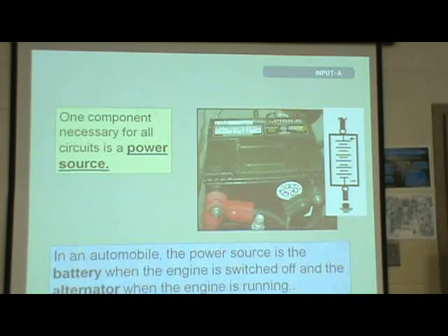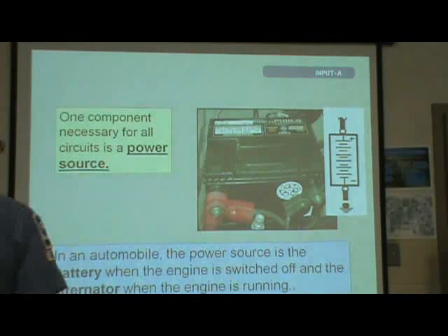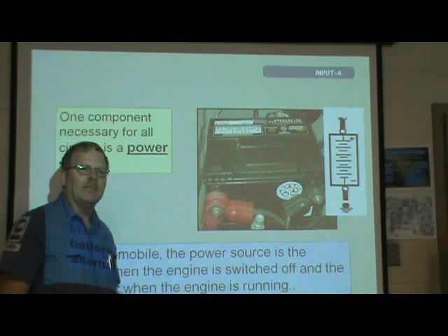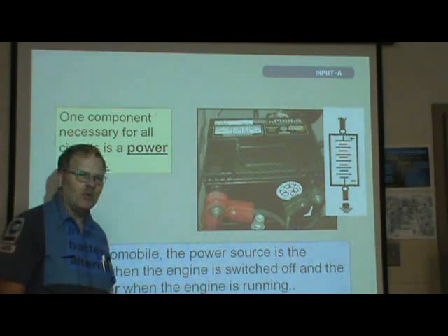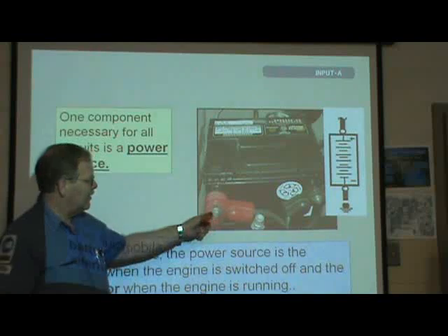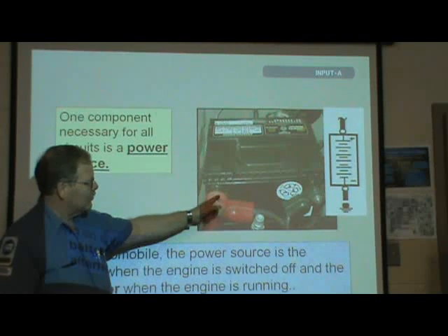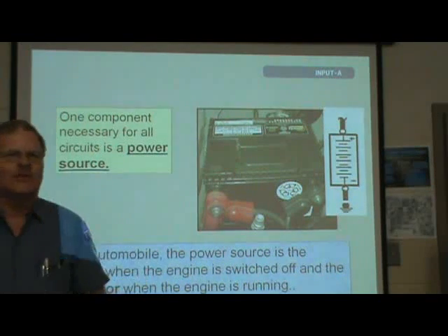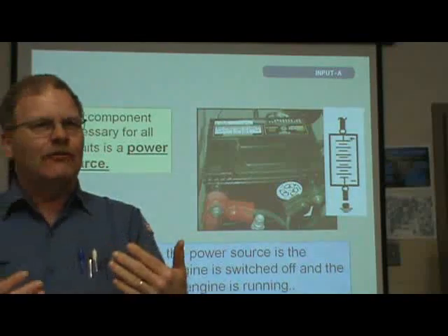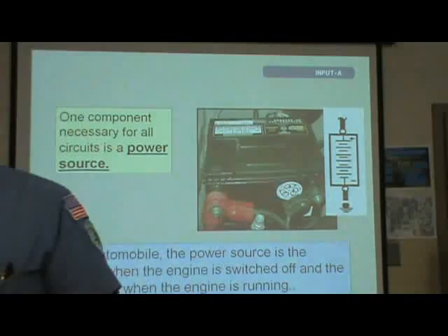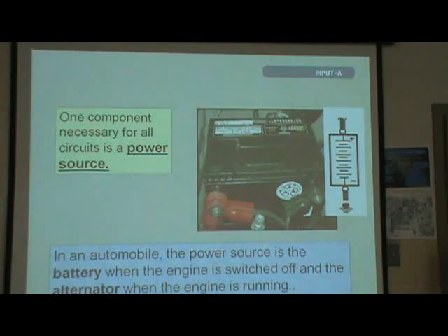All right. So one component, there's your battery. Now, don't we all just love these side post GM batteries? Particularly the one where they run this long bolt through two of these cables. There's all kinds of potential for corrosion in there, and it can look just fine and be so crummy that there's no way it'll ever work.